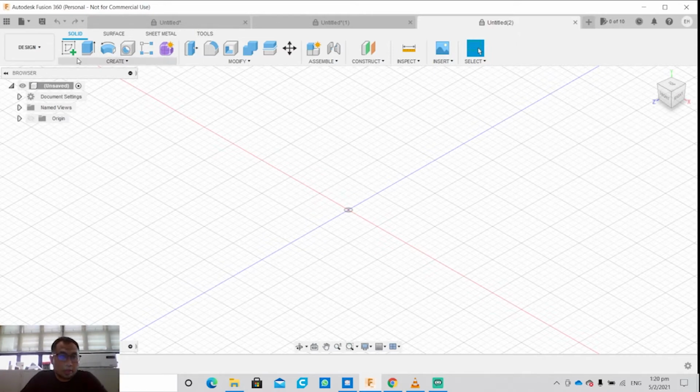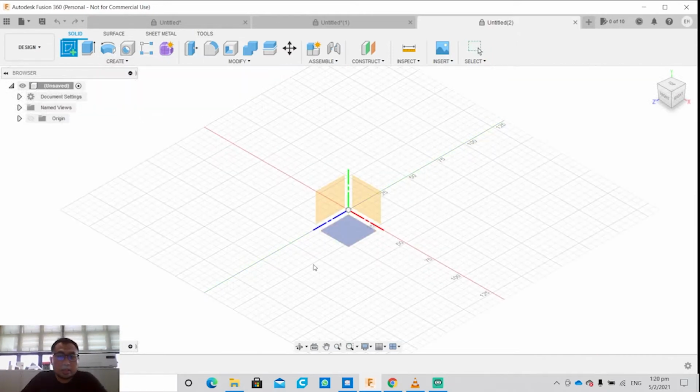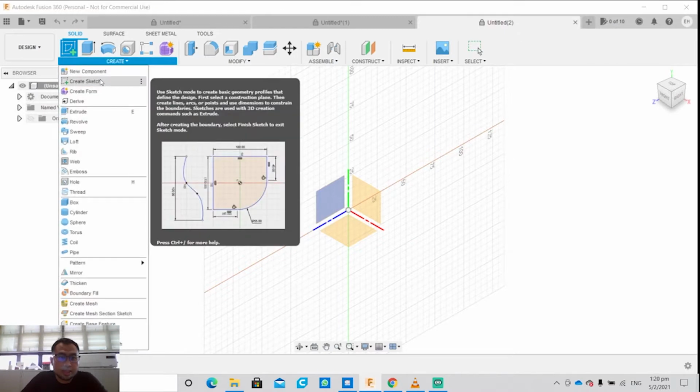So let's carry on under create sketch. The next one, create sketch, is very important. That is where you build your 3D model from a 2D design, and from that 2D design, you extrude into a 3D form. When you create a sketch, you think of your object in a cross-sectional view, and you try to find a way, as much as possible, to sketch the cross-section of your 3D object and then extrude it into the other half, so it's easier for you to complete.